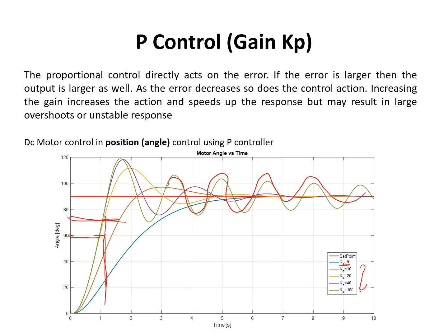I think partly because in this case I put a saturation limit on the controller. In essence, the voltage output can't go infinitely high. We have to physically cap it. So in this more realistic non-linear sort of system, we have limits of the voltage. Adding additional proportional gain doesn't really improve the stability or improve the transient response, but does definitely give you a more oscillatory nature. So there's a limit in terms of the proportional gain. But again, what we see is more proportional gain, the faster response, but the more overshoot we have in our system.